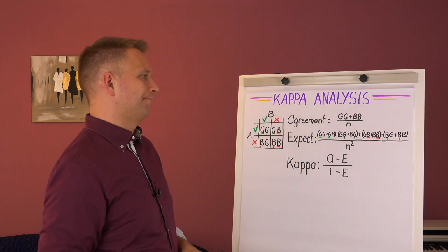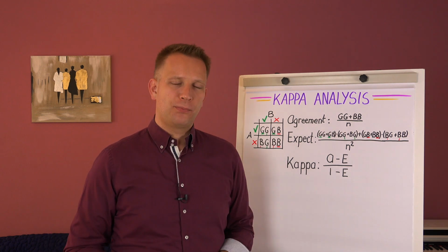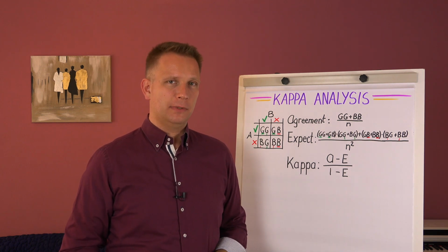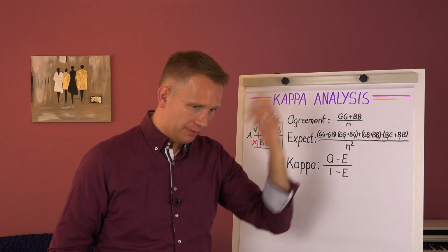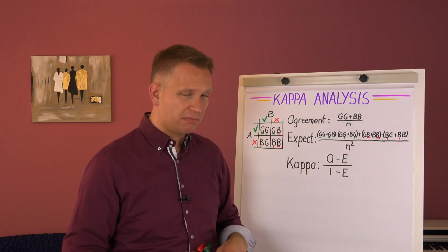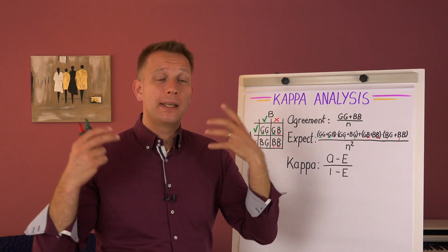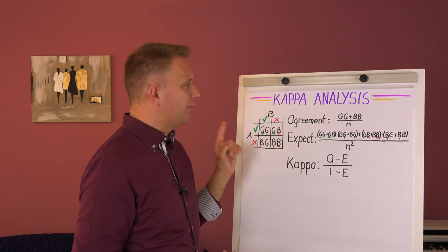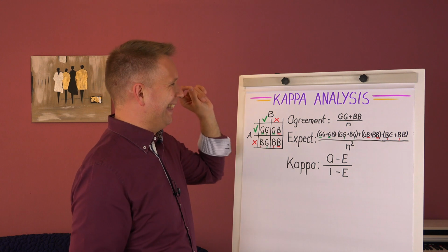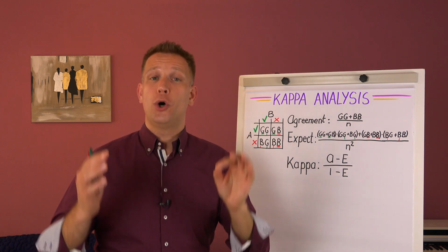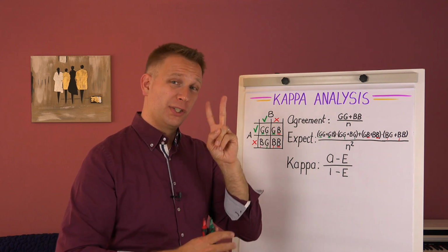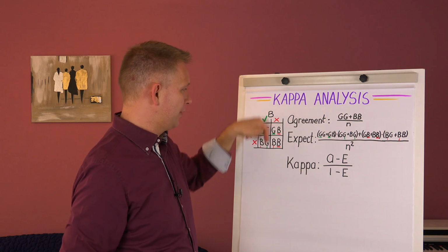But now, the big sort of problem with the Kappa analysis. We had the one with the defect rate, that you need at least a couple of defects, at least 5, so get your defect rate artificially high in the sample that you take. The other really big thing is that the Kappa analysis will only compare 2 operators. This is a 2-way system.